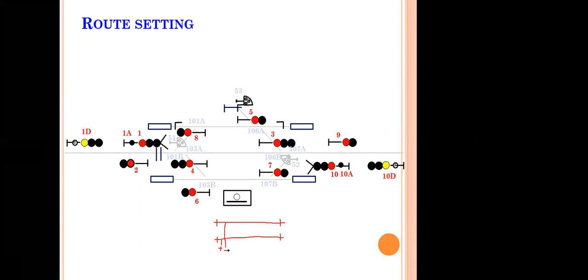You please see here. One rail is connected with a positive polarity, the other rail is connected with a negative polarity, maybe about 2 volts, not very high. At the other part of the rail track, where the track circuit is there, I will connect a relay, an electromagnetic equipment.